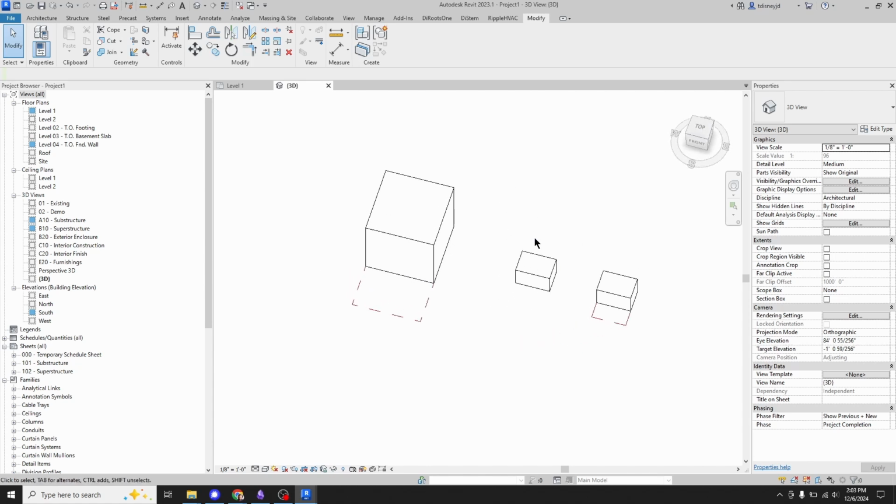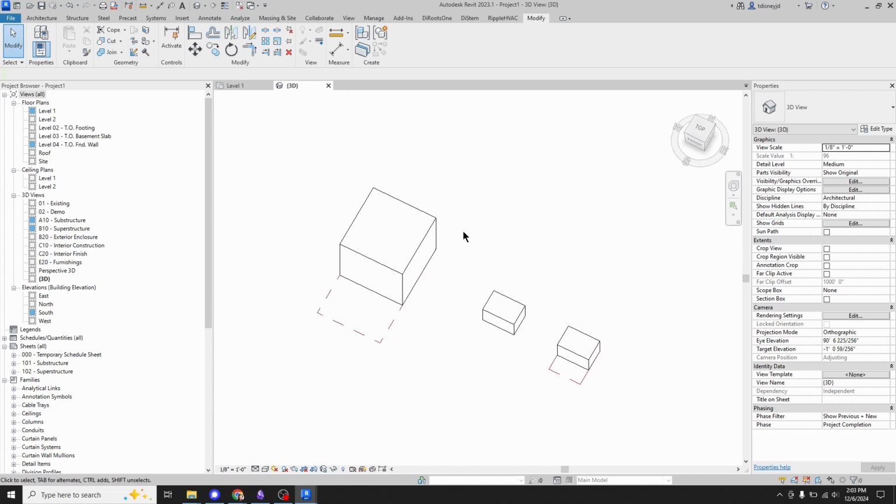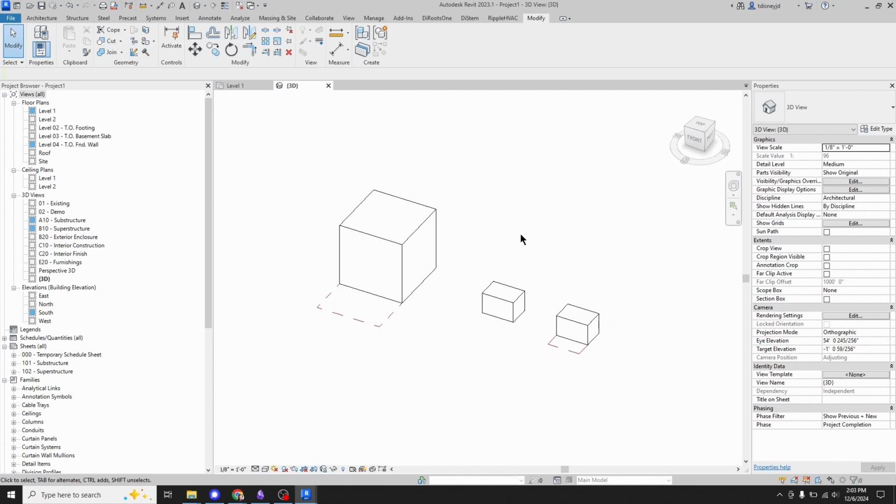This is like a dirty little secret. People don't know it. And it's fast. You don't have to fuss with things. I really encourage people, like, how simple can you be? The nice thing about boxes is they're rarely wrong, if that makes sense, for equipment. They might be not totally clear what it is, except you see the tag and it says CH, and you say, oh, that must be a chiller. And another one says RTU. Ah, that must be a rooftop unit. It doesn't have all the lines that show it. Those lines are great. I'm not saying don't get better equipment. I'm just saying make good decisions about and understand how detailed you really need all of your families to be.